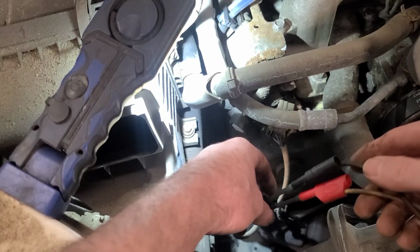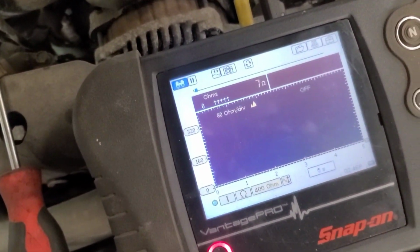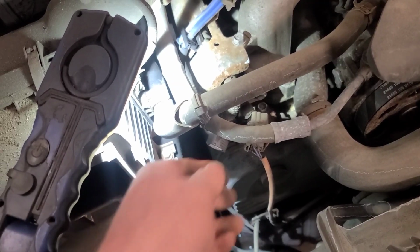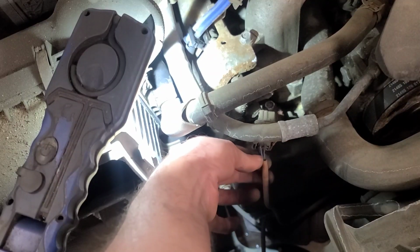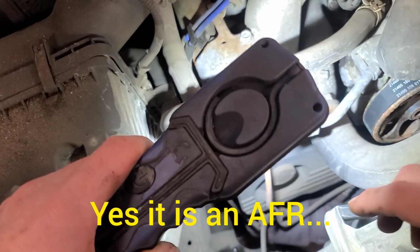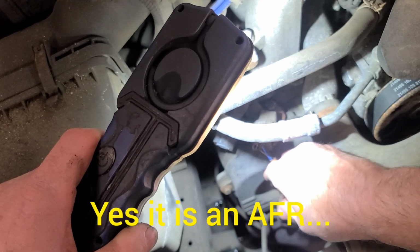And it shows 7 ohms of resistance. So it's not open. Now I don't know if that's correct or not, but fortunately we have another oxygen sensor right beside it. Mind you, this one is maybe an AFR. No, it's not. That one's the bank 1 sensor 2.